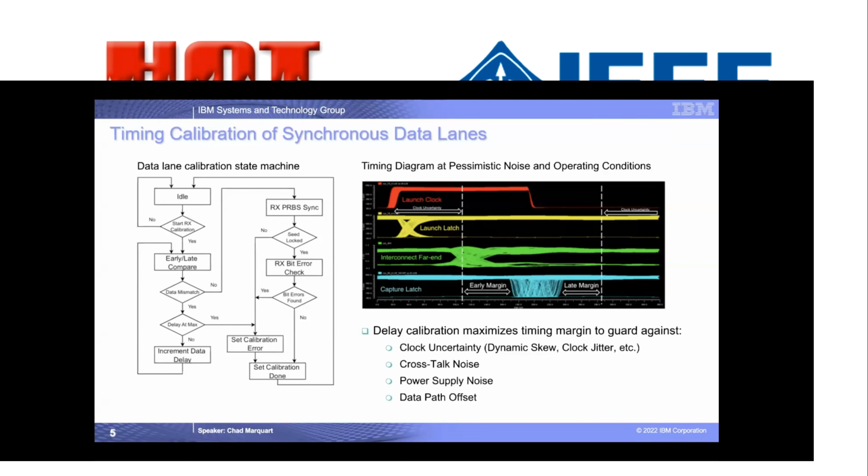Of course, if no delay line setting is found which satisfies both early mode and late mode margins simultaneously, then the calibration routine will exit with an error. However, for the operating conditions of the Telum DCM, this is only expected to occur in the event of a defect in the hardware, or if devices critical to the performance of the PHY are fabricated well out of spec.